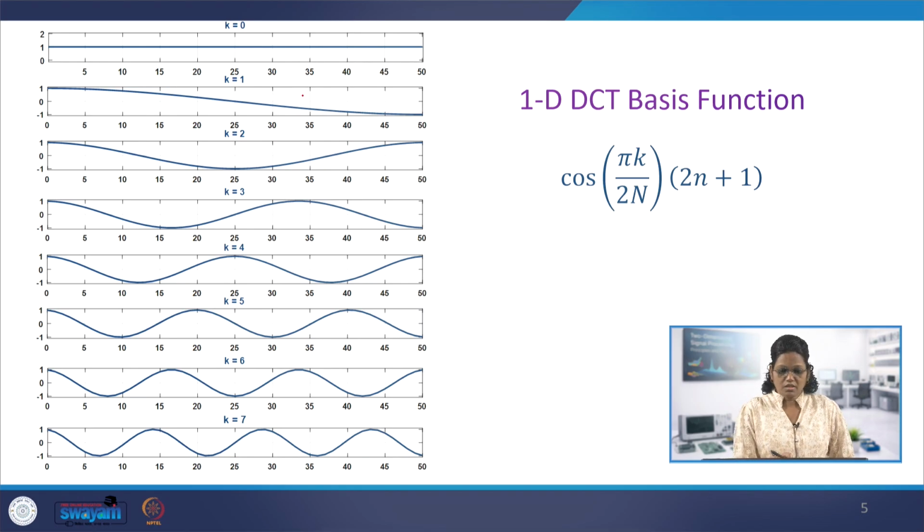So this is the DCT basis function. So why do we need this basis function? Using these bases, when we are computing the DCT coefficients, we are correlating x of n with these k values. If it is correlating, then this type of signal exists in x of n, and this gives the coefficient, or the coefficient is high. Otherwise, the absence of the coefficient can be observed in the correlation function. So this basis function helps in reconstruction as well.